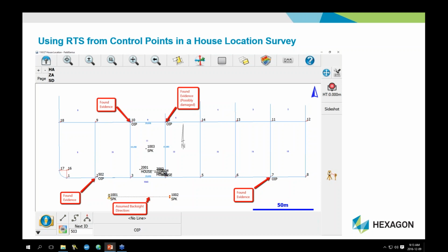And in some cases, say you could resect in this case and get started, and the resection would allow you to get started and sort of get hooked into the plan. But where the resection falls down is you can't add to it later, because it might turn out that one of these pins is displaced. So we would do a local calc to get the first 2, then we would move into the site.